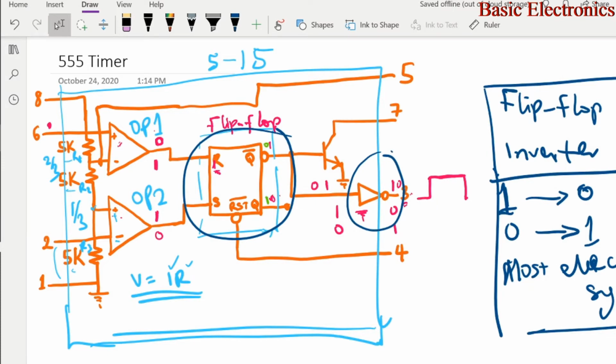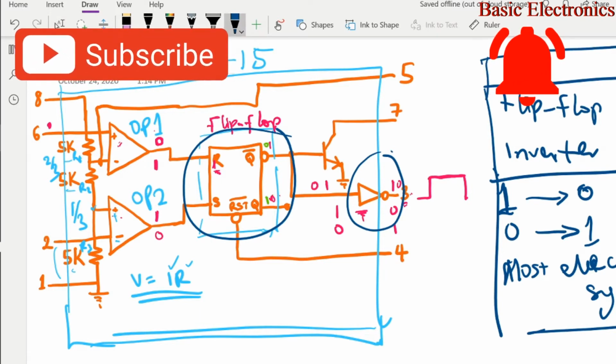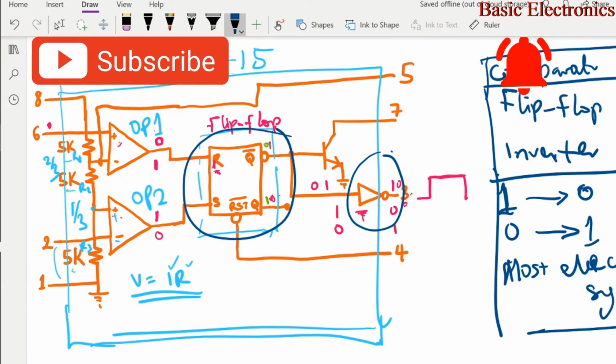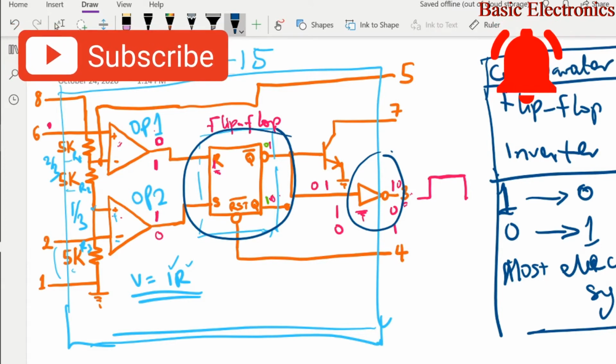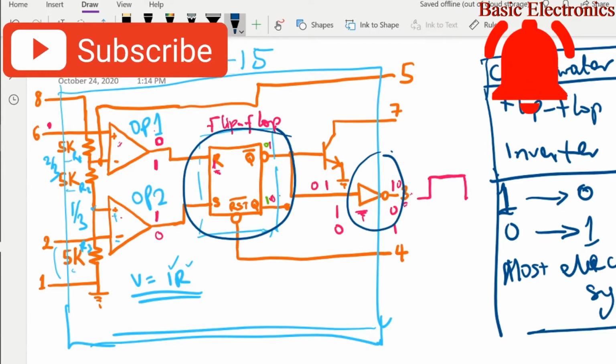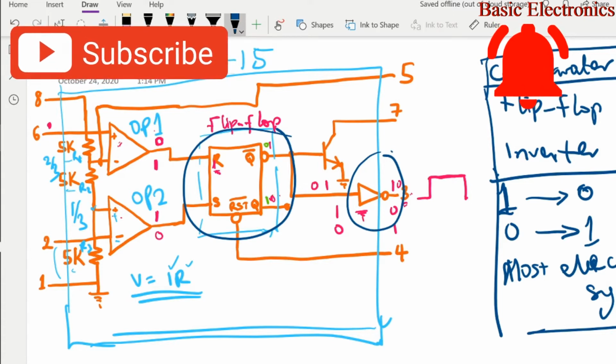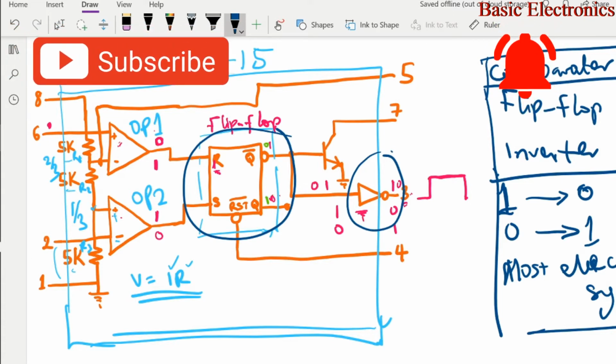on the left hand side you have two comparators. The function of a comparator, again, I think we have to do more service to that. Let's add it to what we're going to be doing in 2 weeks' time. But how a comparator functions in a general sense for today's purpose is that it has two inputs, the inverting and non-inverting input. The positive input is the non-inverting, the negative input is the inverting input.